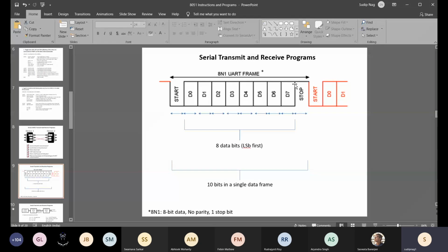If you look at this data on an oscilloscope, you will find a little negative-going pulse for the start, and all the remaining bits are 1. That is how a data frame for FF will look. If it is 00, you can just substitute that on these bits.